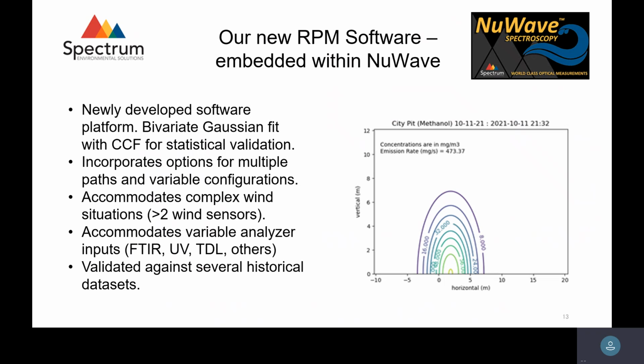So as every meter block or so you go up in height, the EPA method, the OTM-10, basically assumes that. We don't like that idea. We think the wind field is just as important as the concentration field. So the wind field needs to have a lot more variability. So we've incorporated significantly more wind sensors to come up with a wind field determination instead of these assumptions.